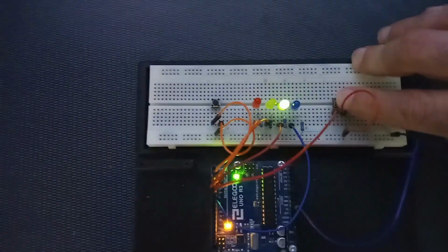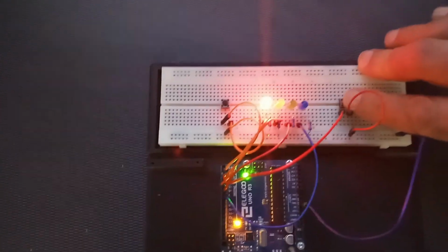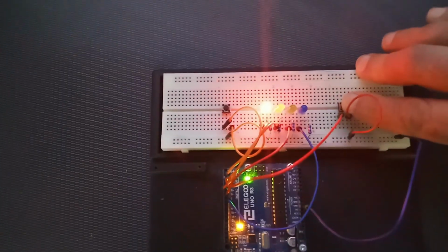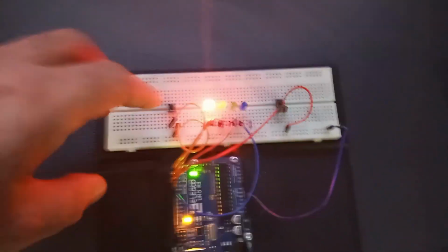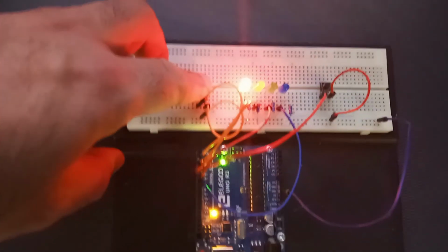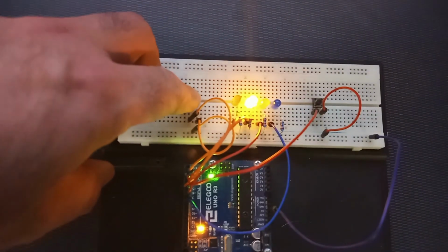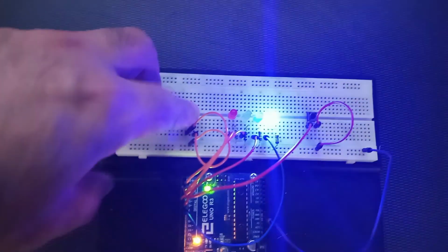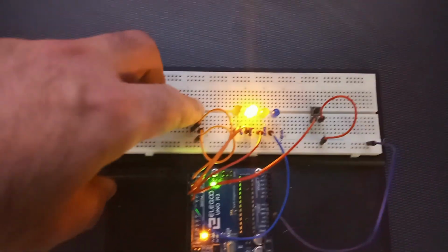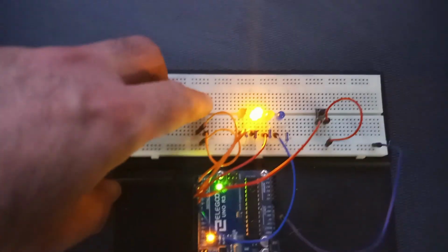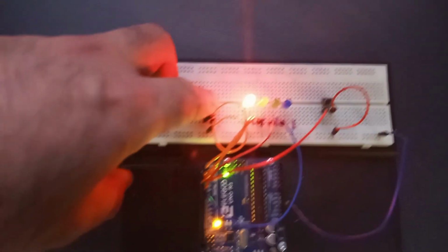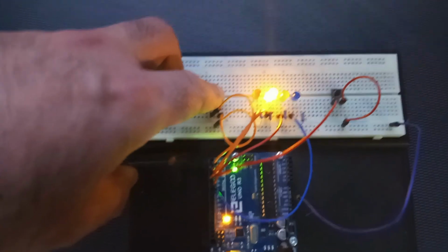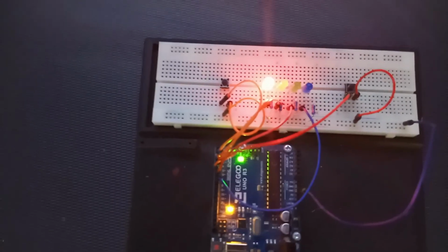And if you hit interrupt 1, obviously it's going to go down. So there you go. So it's working. This button might be a little sensitive. You know, these buttons, they're not the most expensive buttons in the world. So that actually might be what's going on. So maybe a little bit of debounce in there. But it's working. I will put some debounce in there though. Now that I'm looking at it, that's exactly what it is. So I can troubleshoot it and get it done. But anyway, this is my final project. As you can see, it's working pretty good. Maybe a little bit of debounce, but that's okay.